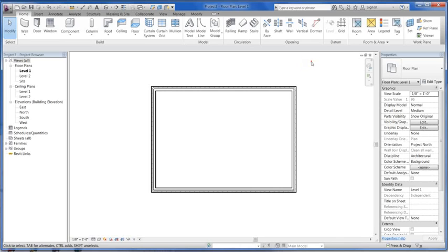If you go to the left, it's a crossing window, so whatever it touches or crosses, it's going to automatically select. So there's a difference right there. You can see it's already got those two walls. All I have to do is touch that wall and it's going to select it. Just like AutoCAD. But Revit has a third way to select.